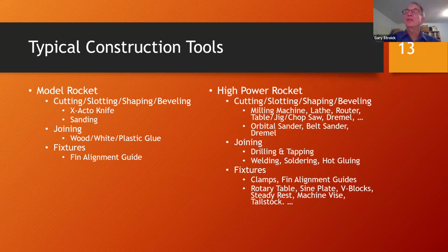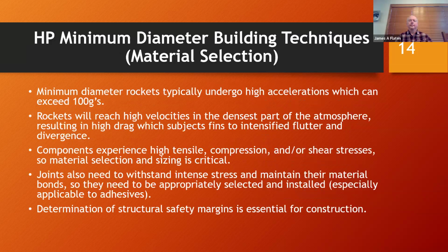And then you'd have a variety of fixtures when you're actually building these particular components, making sure that they remain aligned during the time that the glue is drying. Oftentimes the epoxies, I should say, may take hours to dry. So you probably do want to have some kind of alignment guide to hold the fins in place, or to make sure that when you're conducting some type of cutting operation, it is being done consistently over the length of the material that you're cutting, for example if you're cutting a bevel on a fin. All right. So there's quite a few different tools that can be used. Let's move on to the next slide.